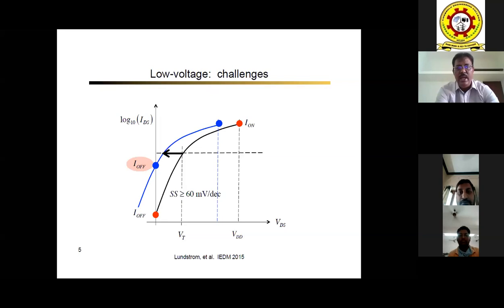So the device doesn't turn off all of a sudden, right? As we can see from the graph, a certain amount of current is still available in the device, and we call this current the sub-threshold current, or leakage current. Some researchers focus on why this amount of current can't actually turn on our devices, and they focus their research within this area itself. So they call it the sub-threshold region. Many researchers explore research possibilities in this area.